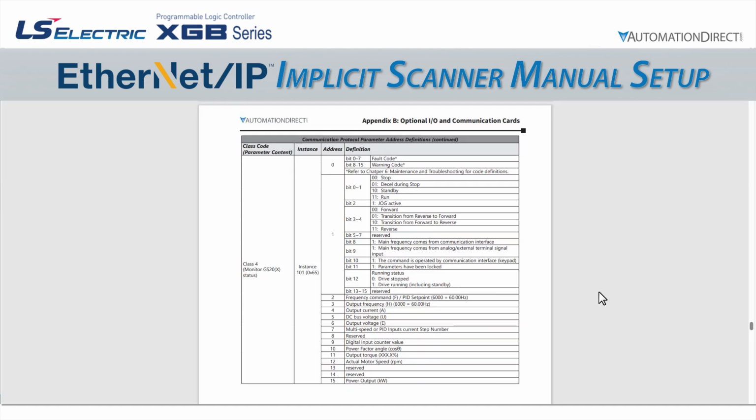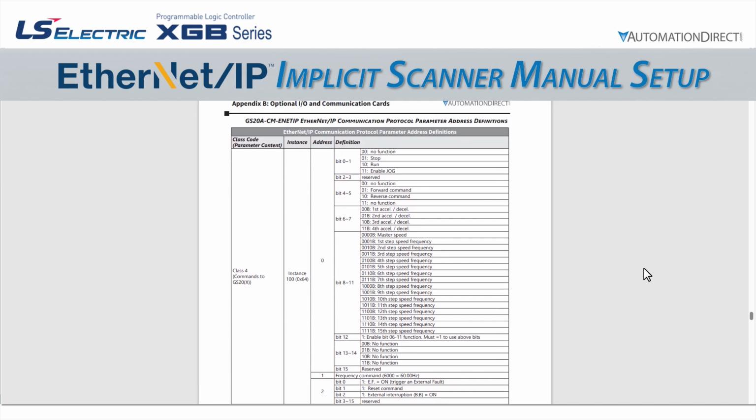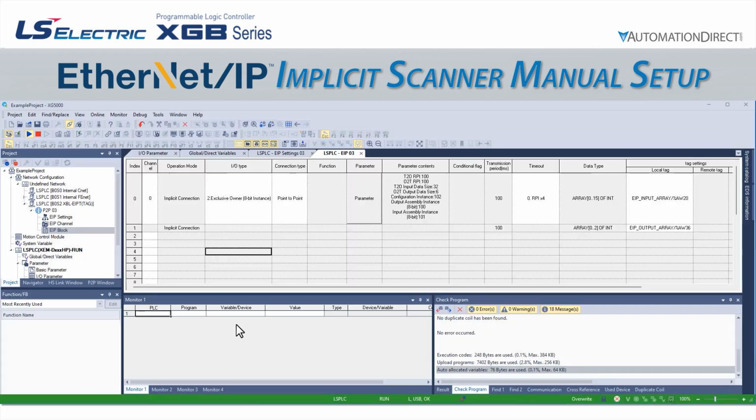If we refer to the GS20 manual again, we see that our input array, element number 3, will tell us our drive output frequency. In our output array, element 0, bit number 1, will put the drive into run mode, and bit 0 will put it back into stop mode. Element 1 will allow us to set a target frequency. Let's add these 3 elements to our monitor window.